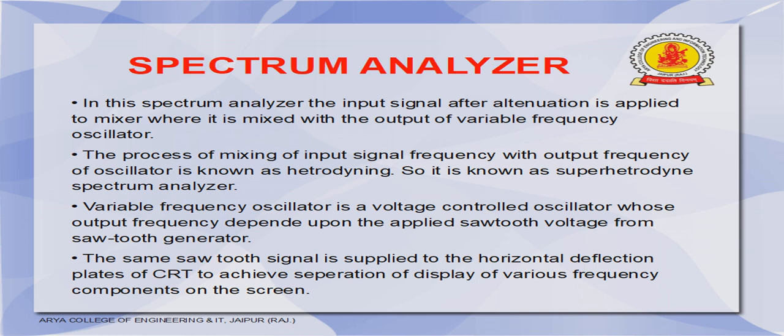The sawtooth signal applied from the sawtooth generator to the tunable oscillator is also applied to the horizontal deflection plates of the CRT, so that the various frequency components can be displayed separately on the screen. The sawtooth generator sweeps the VCO linearly from the minimum to the maximum frequency range, so this type of analyzer is also known as a swept spectrum analyzer.